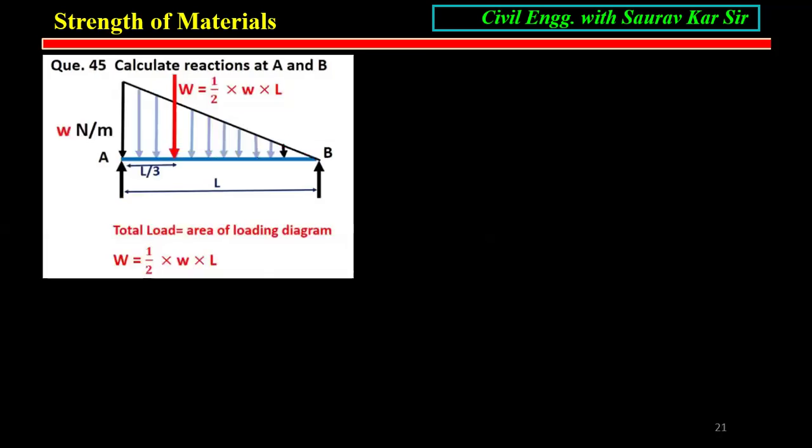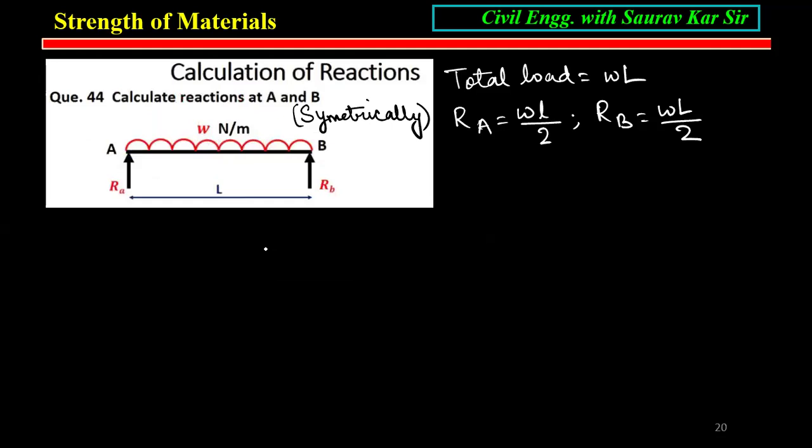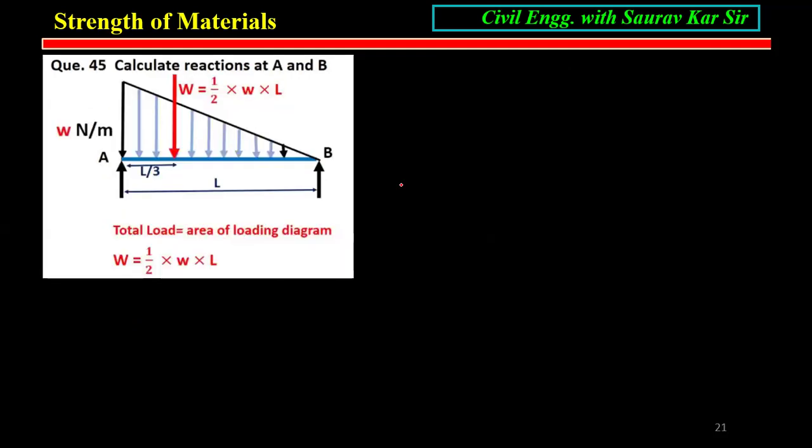Similarly here, in the UDL case, whatever load is coming, that is simply W into L, and the reaction is the load by 2, W into L by 2. Afterwards, I will come to the shear force and bending moment. That is the next case. Okay.